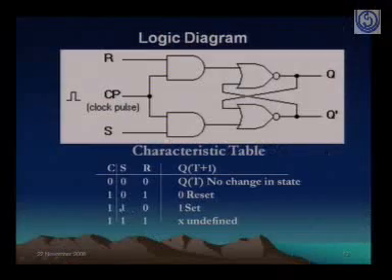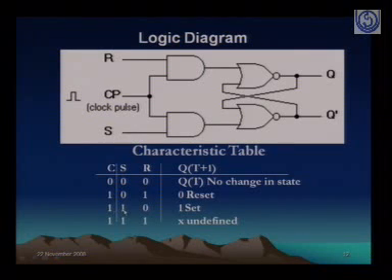For the set state also, once again we have the same, 1, 0, and it becomes set. And finally, when S and R both go to 1, it is an undefined state. We don't know, based on which flip-flop comes or what happens inside.